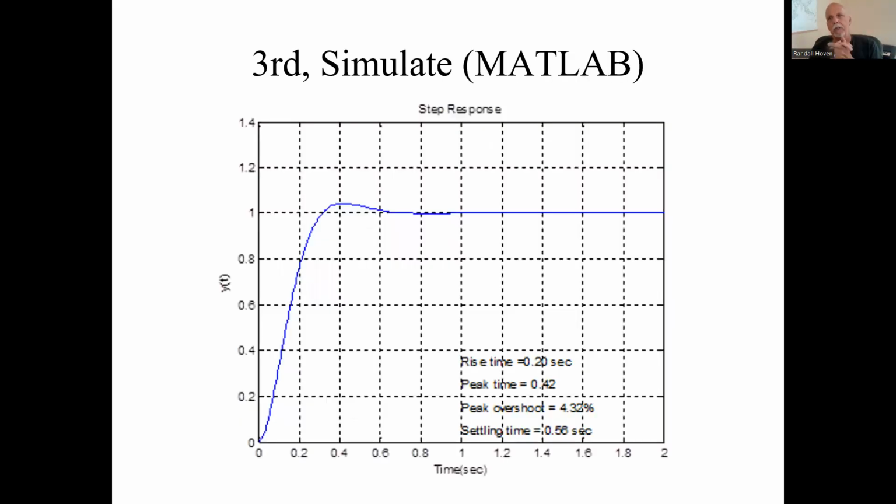Here's where you get into the bigger design process. Here we have to use MATLAB. I'm not going to teach you MATLAB. If you do control systems, you're probably going to have some MATLAB toolbox for controls, or even generate your own programs. This is what that response would look like. And when we calculate exactly, the peak overshoot was 4.2, 4.3 or less. Rise time was right on, 0.2 seconds. So this is pretty close.